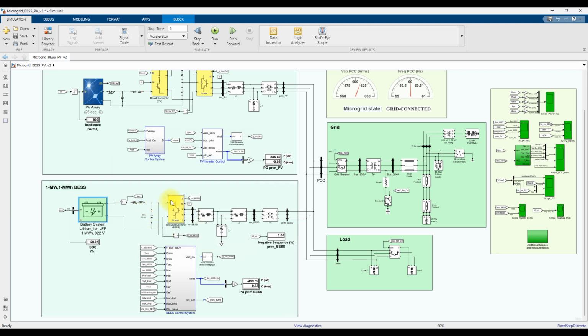Next, we have the 2-level inverter. Here we are not using any converter; the battery is directly connected to the inverter. You just have to convert DC to AC or AC to DC according to the condition of the control logic, whether we go for charging or discharging. Based on that, it acts like a converter or an inverter. Finally it is connected to the point of common coupling.